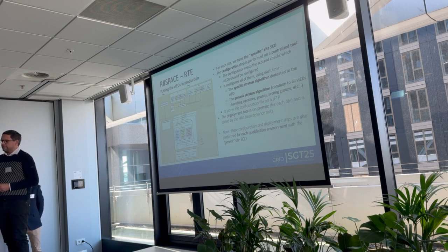Basically, for the virtual IEDs, it will check the different virtual IEDs in the SCD, and it will take the specific Straton algorithm. For instance, for the circuit breaker failure algorithm, it will take the specific Straton algorithm for this particular function. It will also take the generic Straton algorithm, meaning, for instance, how we deal with operates, GOOSE, setting groups, and so on.